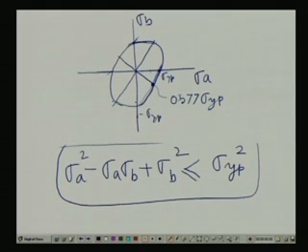Now, this is the envelope within which the stress in the machine element is in a safer zone. In that case we should not consider the equality, as the equality means this is just the boundary. All the stress points can go at most up to the boundary; inside it is safe, outside it is unsafe. So, this is the idea of the maximum distortion energy theory.